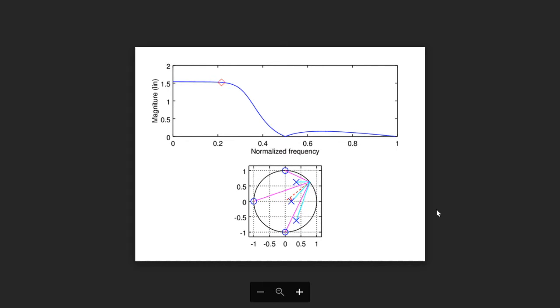And then these poles are located so that you can get a flat passband response. So that's basically the principle of how to locate those zeros and poles. You can adjust the gain of the system with those poles, and it's more cost efficient than using the same thing with the FIR system, meaning the zeros. You can flatten the passband also with the zeros, but okay, I think we will go through that tomorrow.